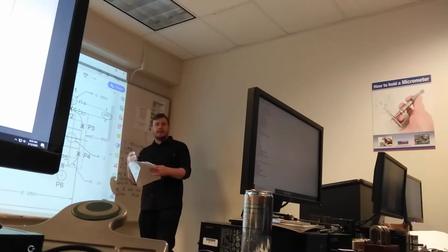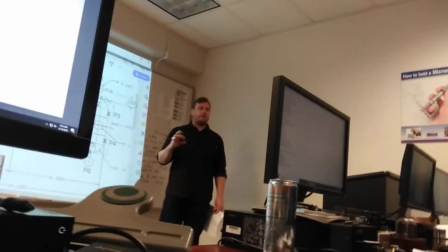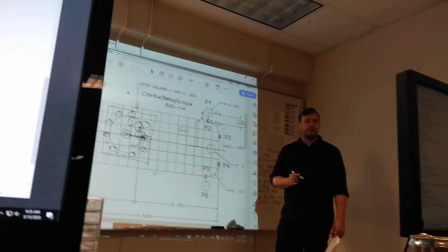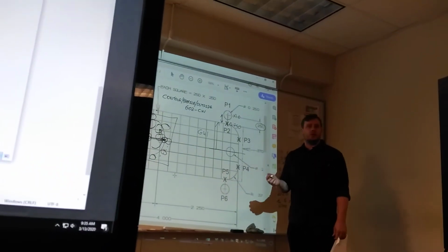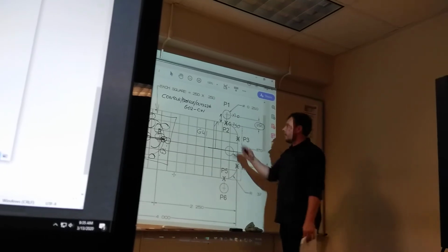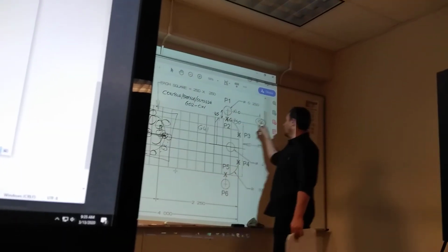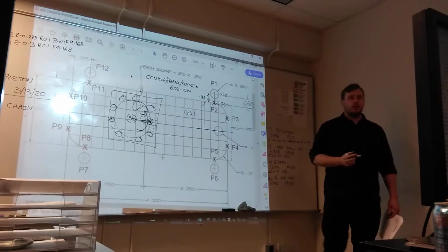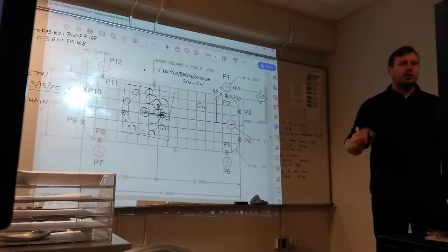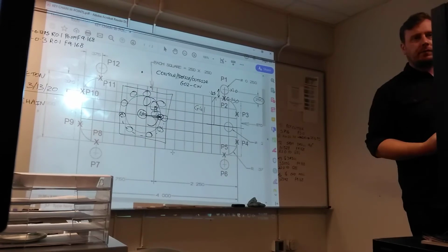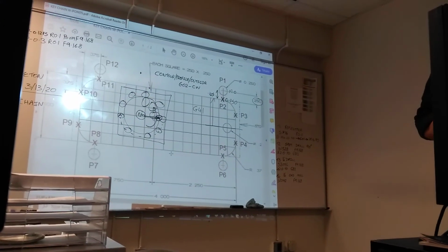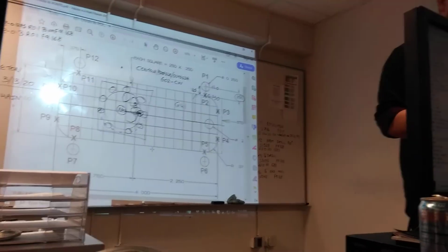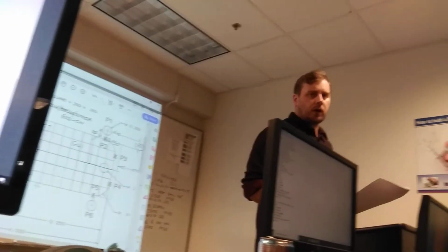This is telling you it needs to be at least half of the tool. What size is our tool? .250. So what's half of the tool? .125. We're more than .125. We're good, right? It needs to be at least .125 away from the part. At least. More is better. You've got clearance. So always start the tool off the workpiece.